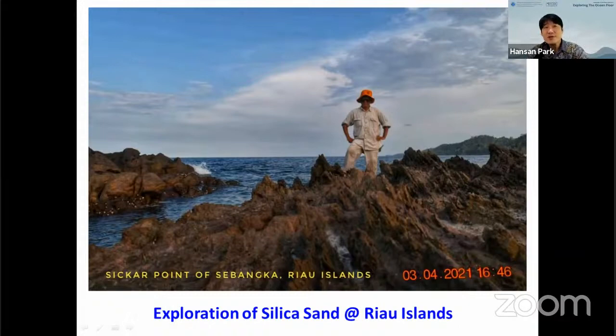Yes, actually our equipment just fits shallow water, I mean 100-meter water depth. Within 100 meters, our equipment has very high resolution with a multibeam echo sounder. So if in the Sunda Sea there is some kind of channel or volcano, maybe our multibeam echo sounder can detect changes of topography under the sea. But maybe we also need seismic sensors to confirm the shape of a channel or a volcano.